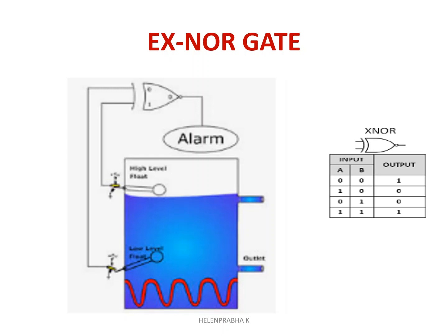So you can use this based on this truth table, wherever you want. Suppose you can take this example. Here both the levels should be the same. It should not go for high or it should not go for low, right? Either both should be high or both should be low. Then you will get an alarm, right? So for that case you can use this exclusive OR. So a lot of applications are there. You also try at home. Thank you.